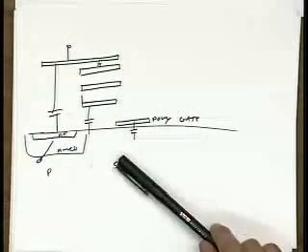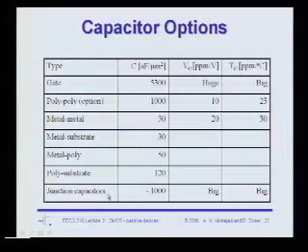And going back to our list, of course, if we can build a PN junction, we also have a capacitor. So these are the options available to us. They all make sense in certain applications, so there's no magic bullet. But increasingly nowadays in a modern CMOS process, you have high density metal insulator metal capacitors available to you, and they're very linear and have very good performance, and we'll look at some numbers a little bit later.